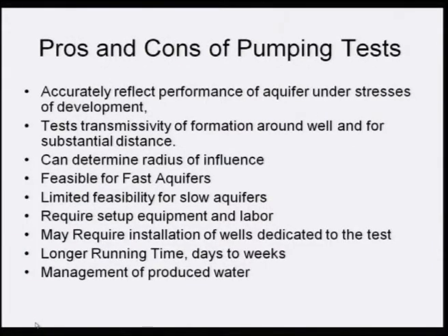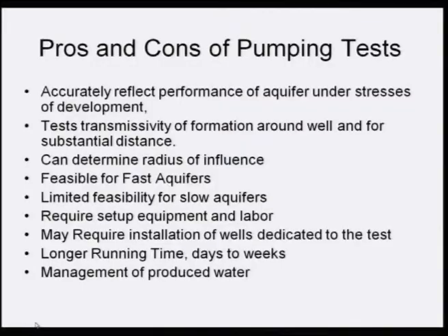And what are the consequences of pumping tests? Accurately it reflects the performance of the aquifer under the stress of development, and tests the transmissibility of the formation around the well for a substantial distance. It can determine the radius of influence, how far it will influence. It is feasible for a fast aquifer, with limited feasibility for a slow aquifer. It requires a set of equipment and labor, may require installation of a well dedicated to the test, and it requires a lot of management also. So, this is all about the aquifer.